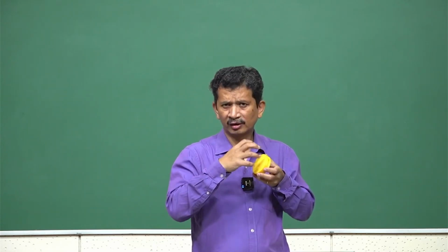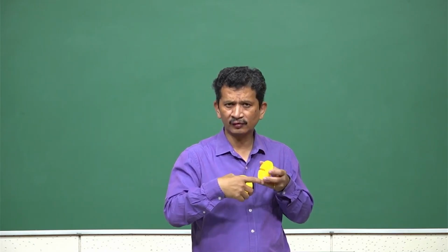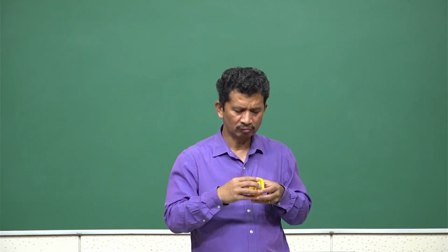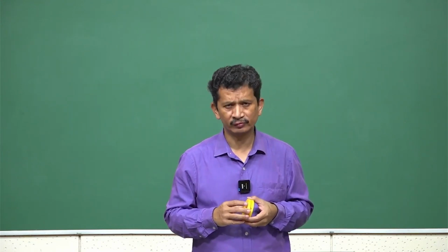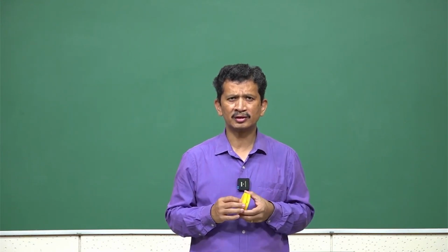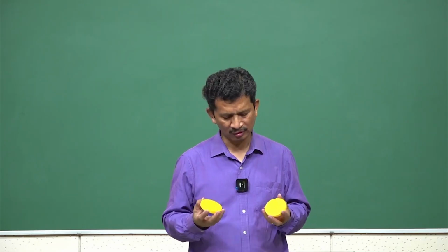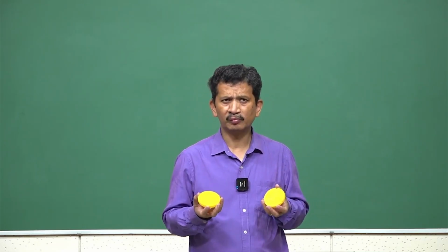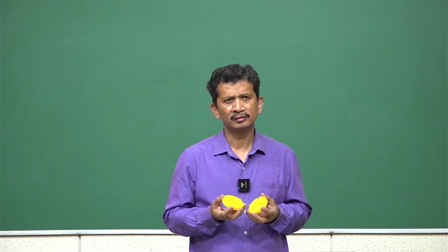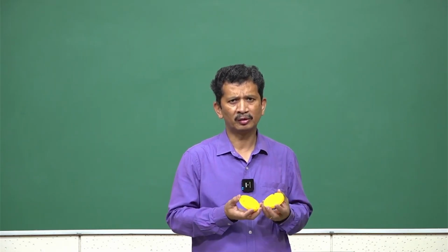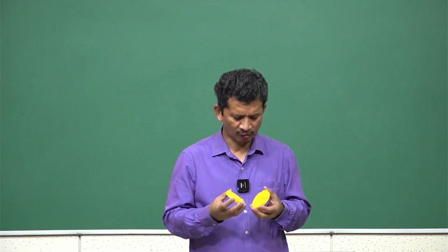It will just radially expand and contract, and the individual ball can slide on the grooves, so it does not provide any kind of thermal stresses also. So, there will be no stress buildup because of the thermal expansion or contraction. So, again very good example, and that is why it is used very often by optomechanical people or by physicists in the old time. So, that is why it is called Kelvin clamp.